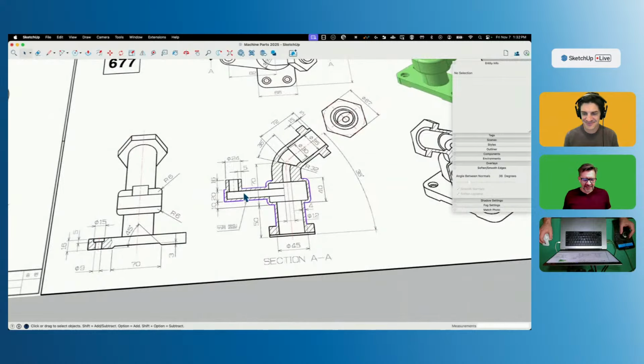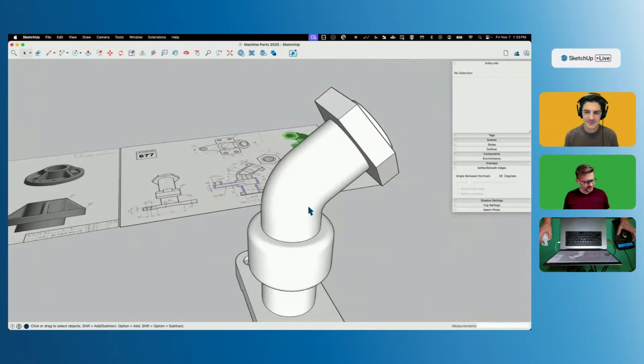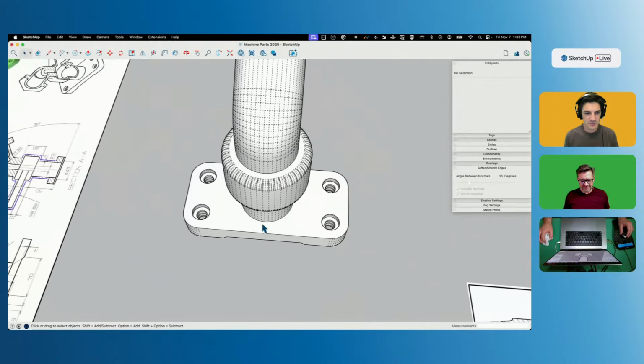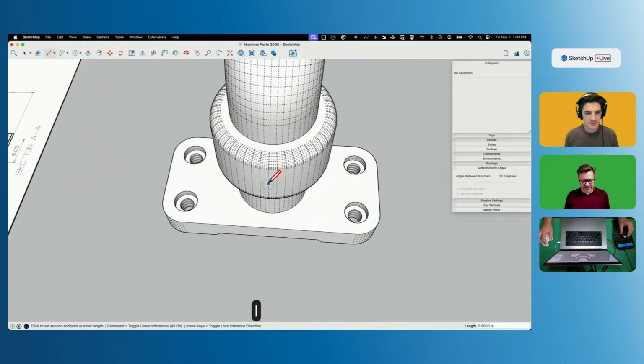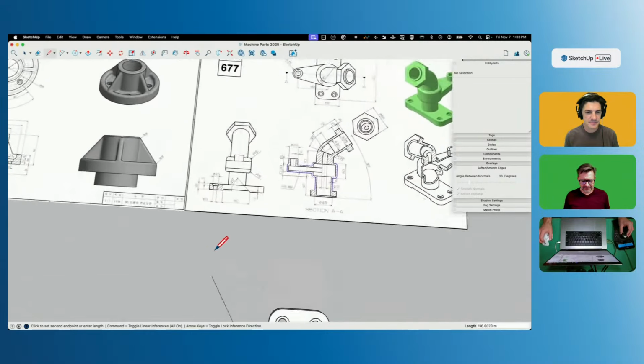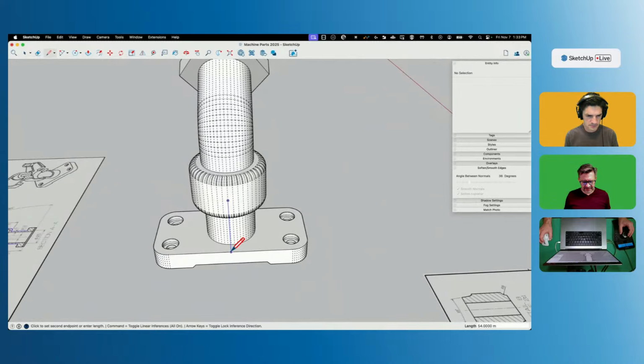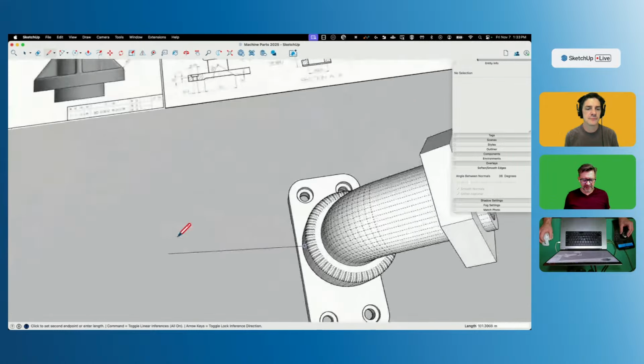I think this piece, if I turn on my hidden geometry, I think I can find and use the middle right here. I'm fairly certain that's the middle. Yep, looks good. I could verify that's the middle, actually. If I go straight down and I snap to the middle piece, see this inferencing the middle there is verifying that that is the middle there.